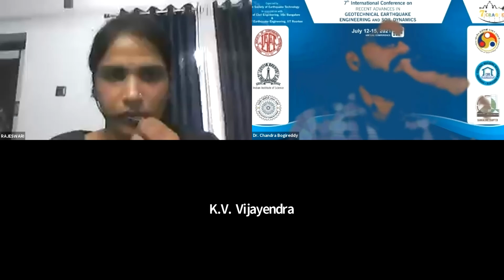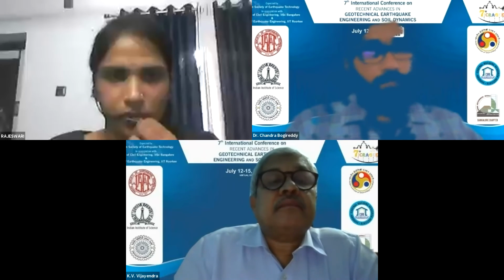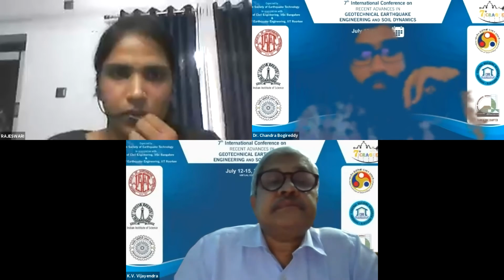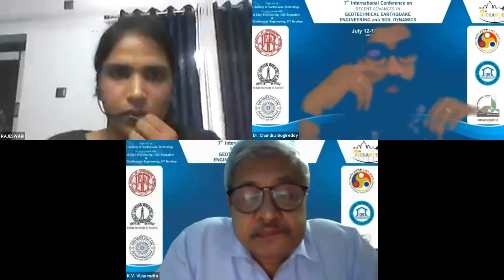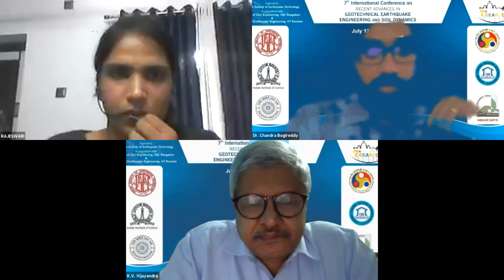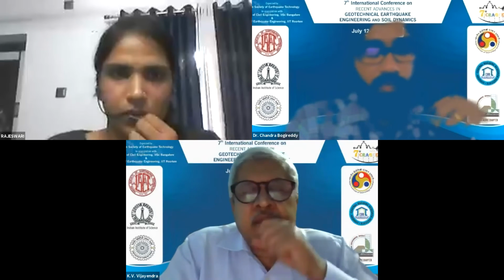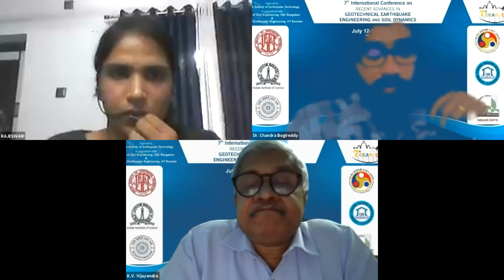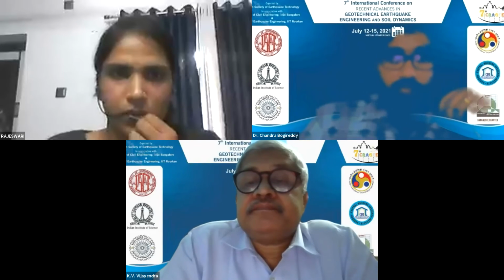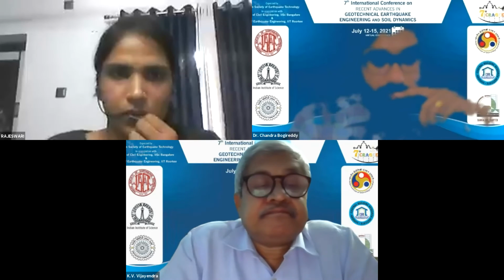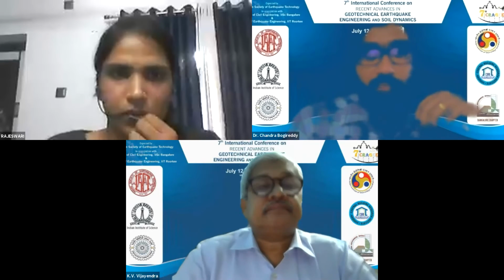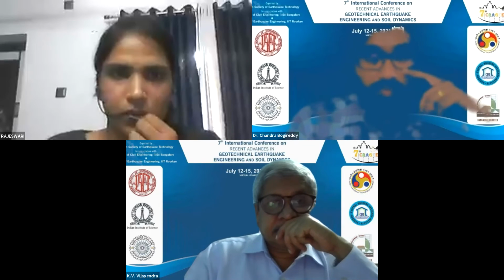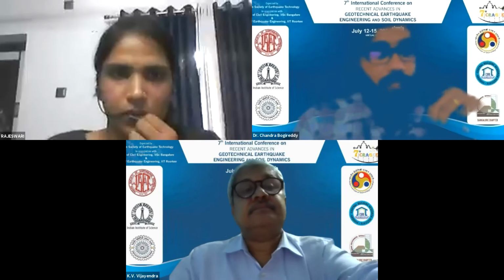Sir, first is a comparative evaluation of behavior of vertical and batter piles in laterally spreading soil. In our study, we have found that the positive batter piles give a better performance compared to the negatively inclined batter piles and the vertical piles. Second is a study of the effective shape of PY curves used for the liquefiable soil. From that, we have found that the conventional concave PY curves underestimate the pile response in the laterally spreading soil. The third is that we have developed prediction models for maximum bending moment for both single vertical and batter piles. And finally, we have calculated the probability of failure of the soil pile systems.